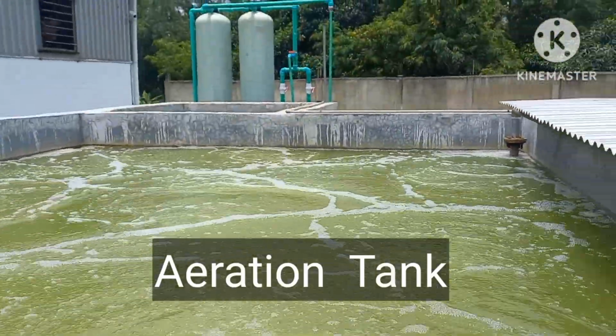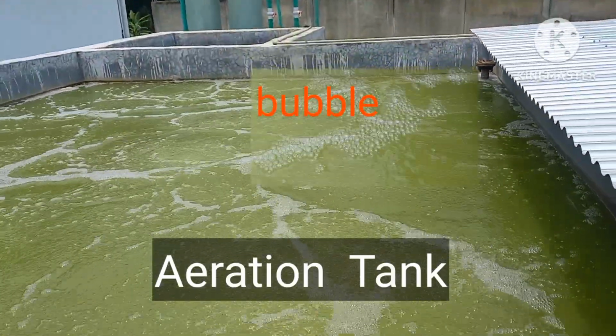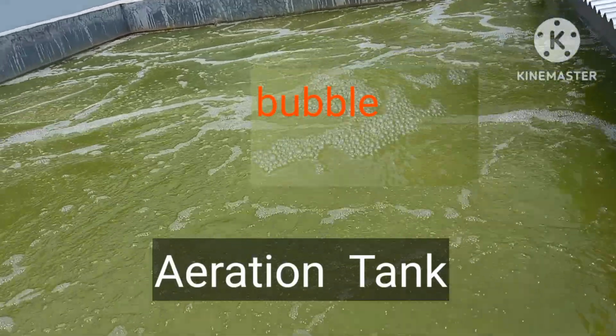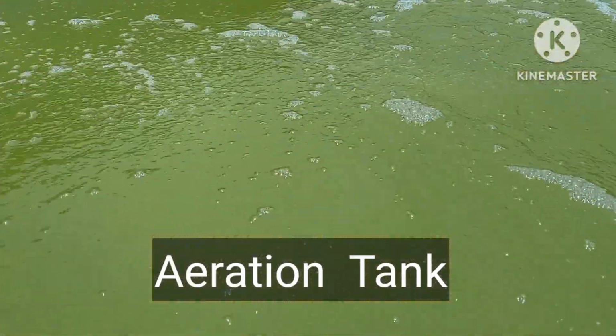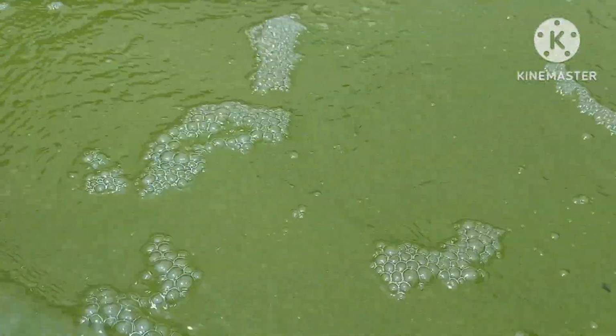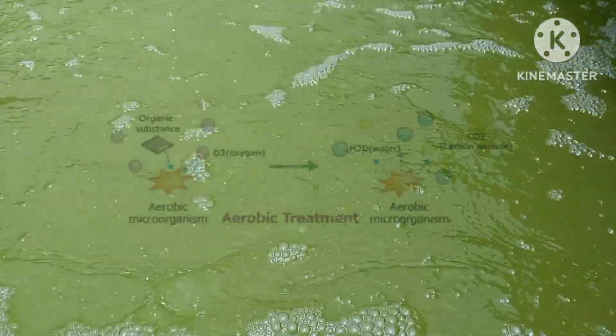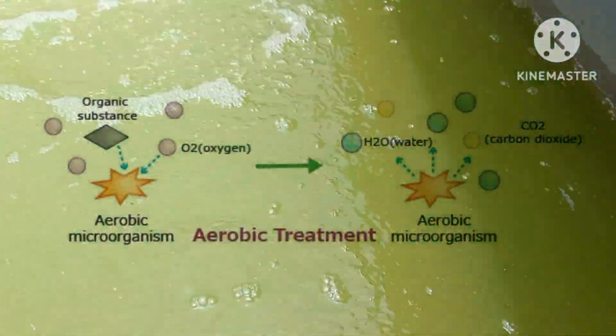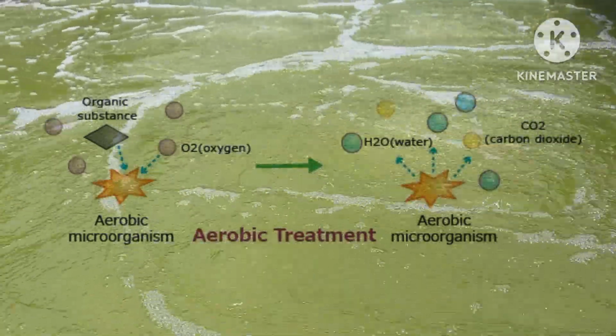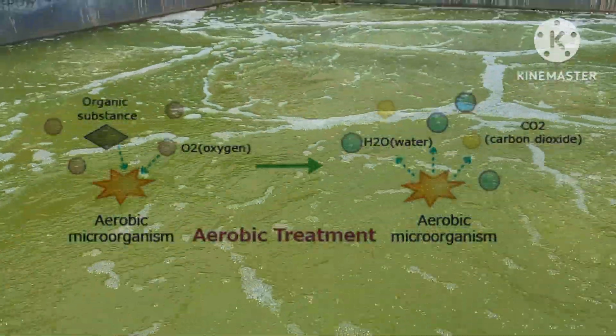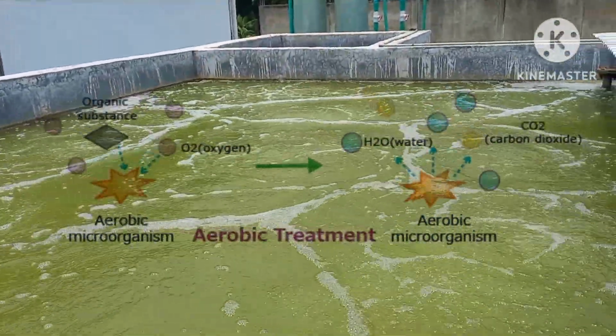In the aeration tank, bacteria are kept in contact with the effluent to be treated for a long lapse of time, that is between 30 and 80 hours. Aerobic bacteria are used to stabilize and remove organic material present in the waste.